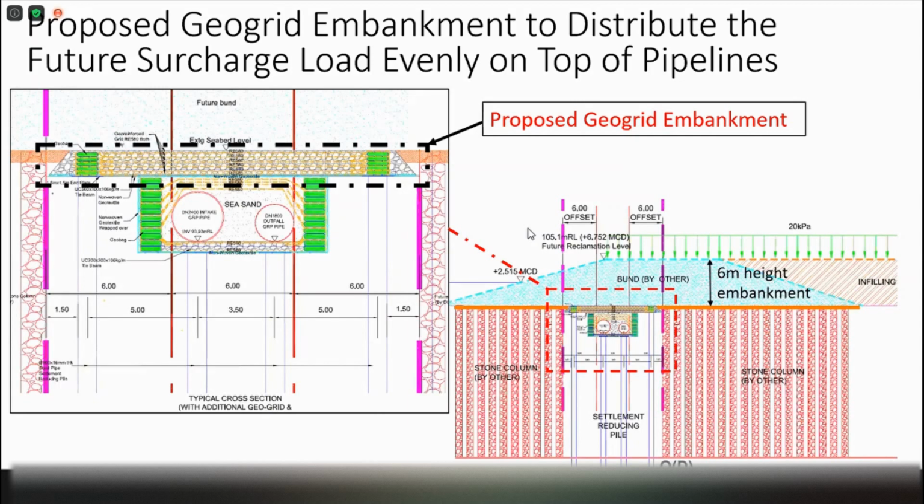So because this pipe is being laid under the seabed of the reservoir, we actually wanted to protect the pipe from dredging and from potential scouring. So instead of using the conventional armor rock, we actually use geogrid wrapped around the sandbag, acting as a reinforcement to provide the protection to the pipe. So you can see the application of geogrid is really up to your imagination.